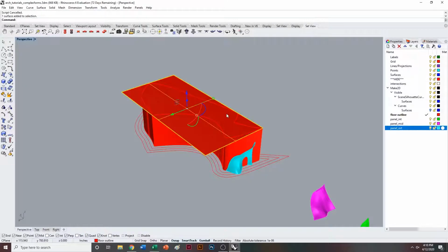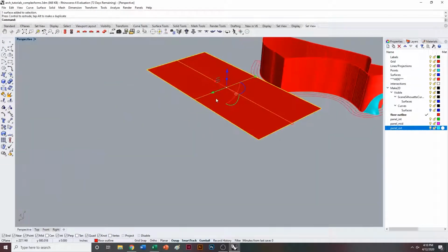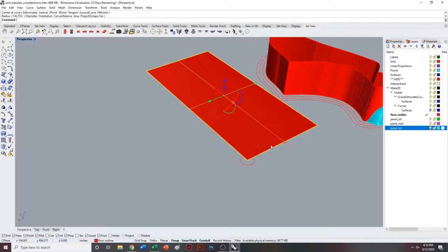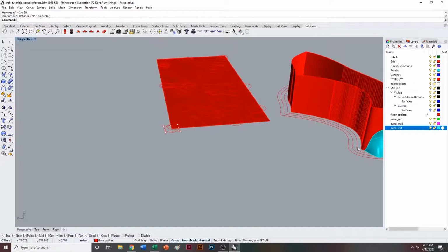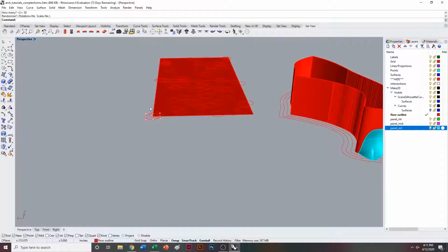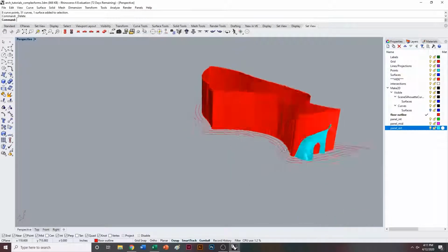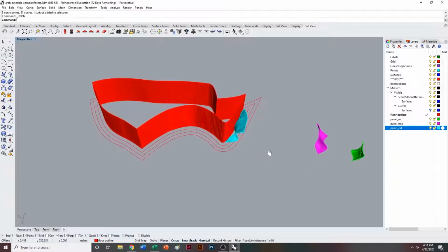so we're actually not going to use the sprinkler command. Basically, how it works for future reference is if I have a plane, and I type in, let's say, circle, I can put that on the surface and run sprinkler. I can click on that surface and it'll array a bunch of random ones along that surface. The reason it doesn't want to do this is because this shape is really complex and the surface is really complex, but it's a good command to have installed in Rhino, even though we are no longer going to use it in this tutorial.